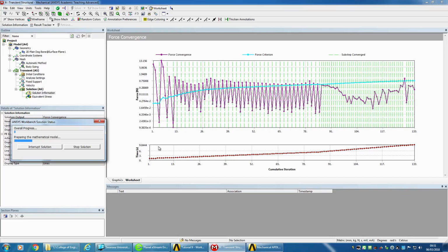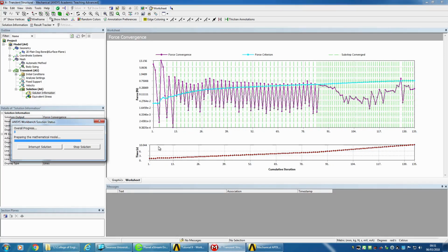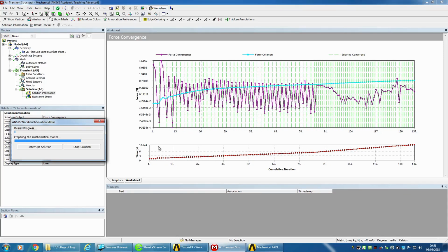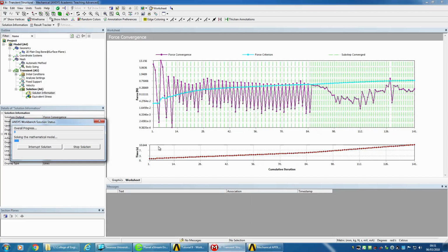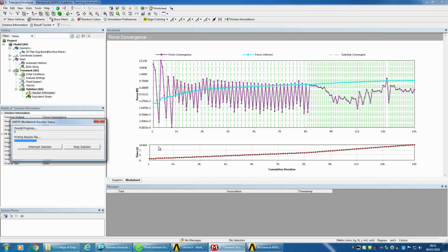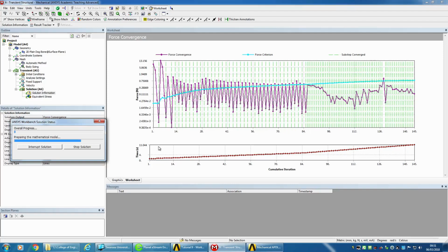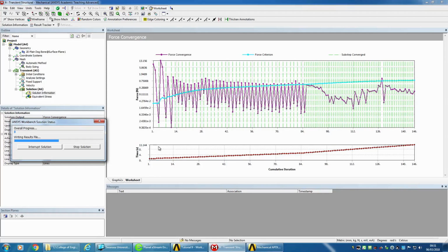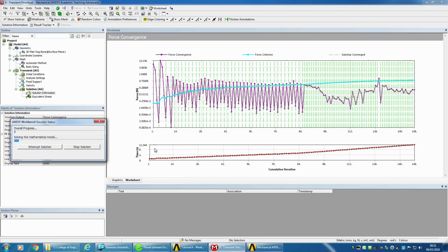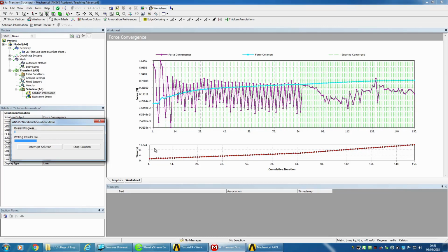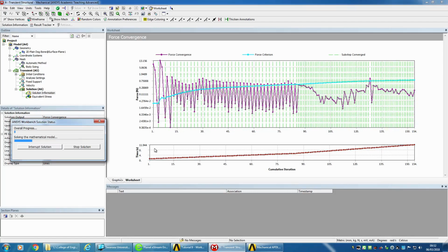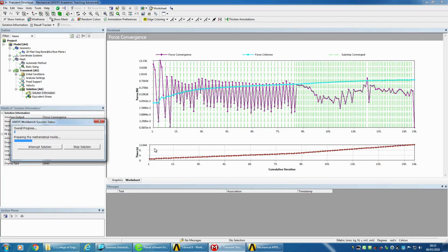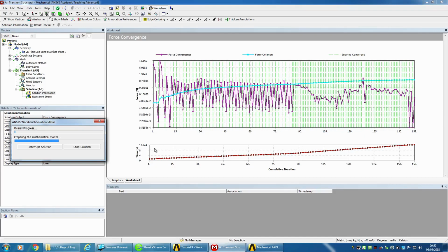But what it can't do is do exactly the same as a tensile test, where it gets up to the upper tensile strength and then fails. It doesn't match the failure point, so you've got to watch that and see how closely it matches. That's when it gets a bit messy, and you'll start to see the convergence getting a lot of red lines coming in, telling you all sorts of errors are going on. Anyway, having waffled on for a while, I still haven't managed to get it to converge, so maybe we'll give it a couple of seconds to run through.